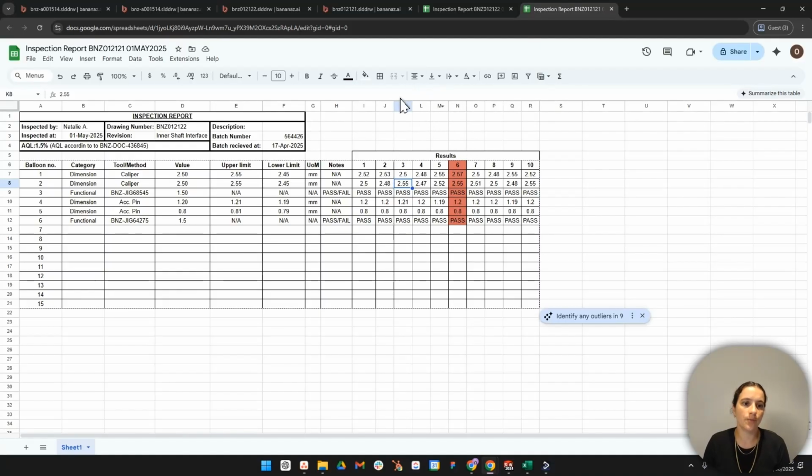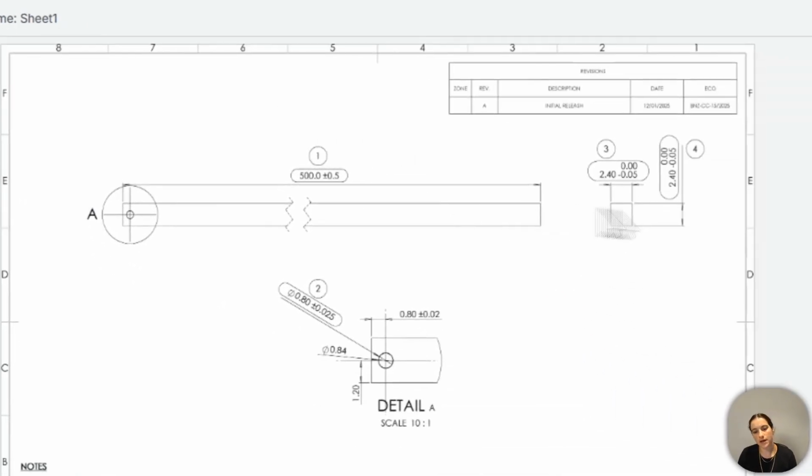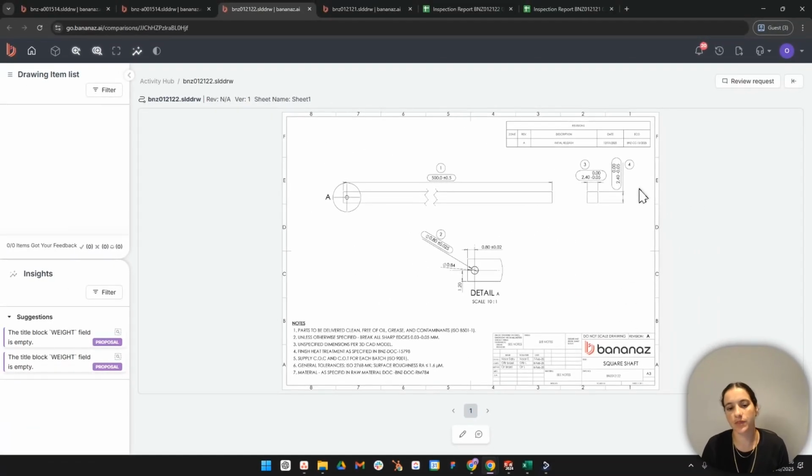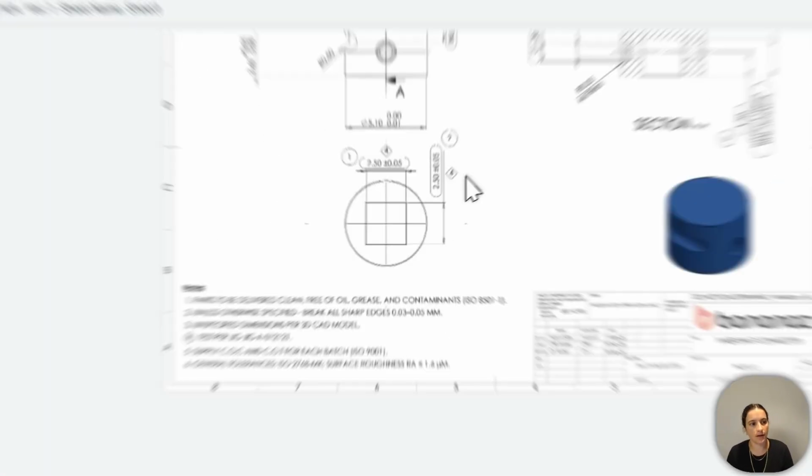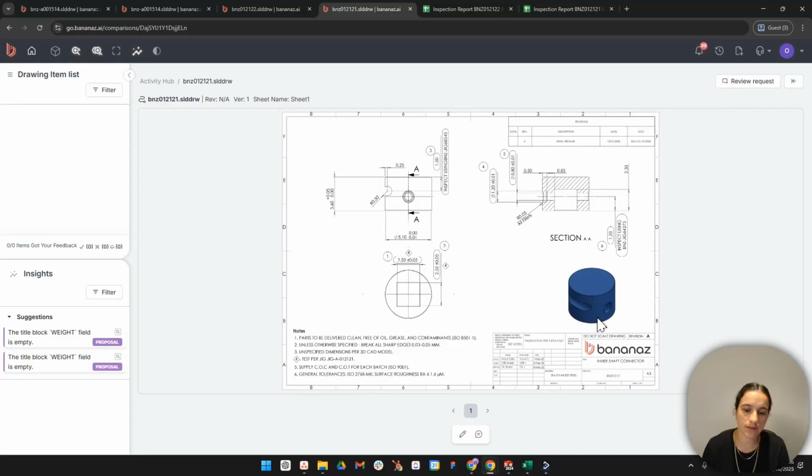Okay, so because the shaft is actually a shelf item that we just cut to the length we want, I can't do much about it unless I change the entire shaft we're using, and I don't want to do that. So I'm going to make changes in the shaft interface part, the connector.